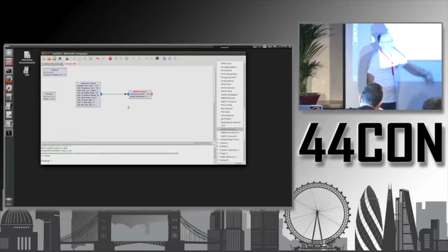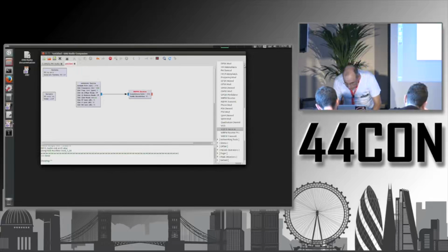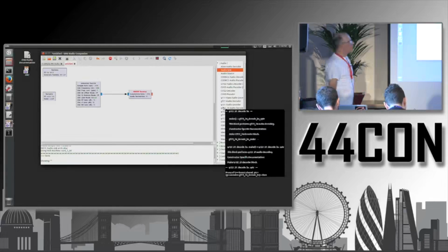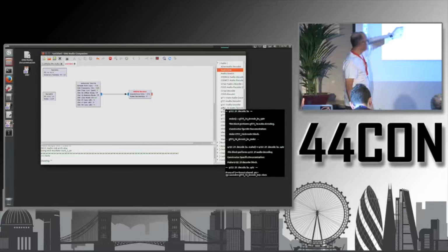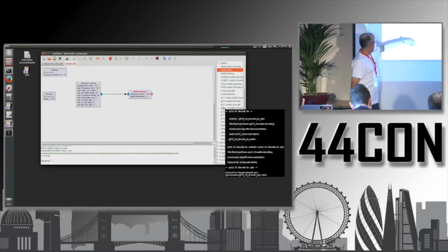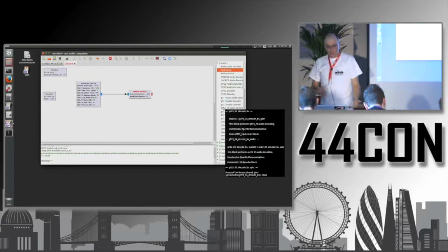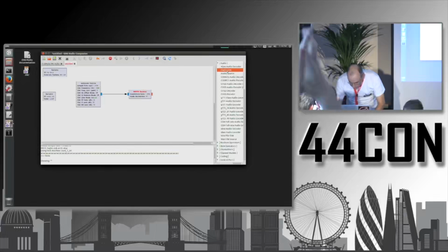And now here we have an audio signal coming out. You can listen to that audio signal with an audio sink. So if you go at the top into audio, you have here an audio sink. So these are sources. They consume your data from devices like the software-defined radio device, and then you also use sinks. Sinks, they produce output. For example, an audio sink is connected to your speaker. So you can drag this into the diagram.